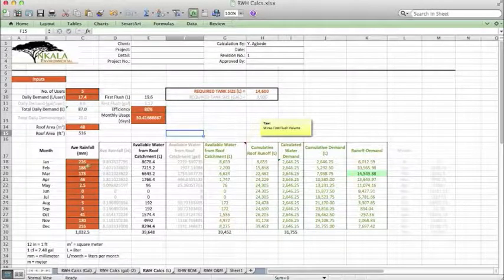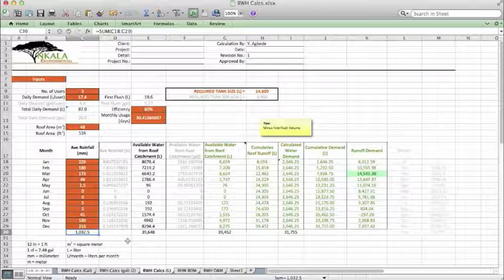The next set of inputs is our yearly rainfall. So we want to not only have that, okay, in this particular region we have 1,032.5 millimeters of rain. That's only going to get us so far for our design. What we really need is the monthly distribution of rainfall. So here is what I have, and this is a different region than Ghana.